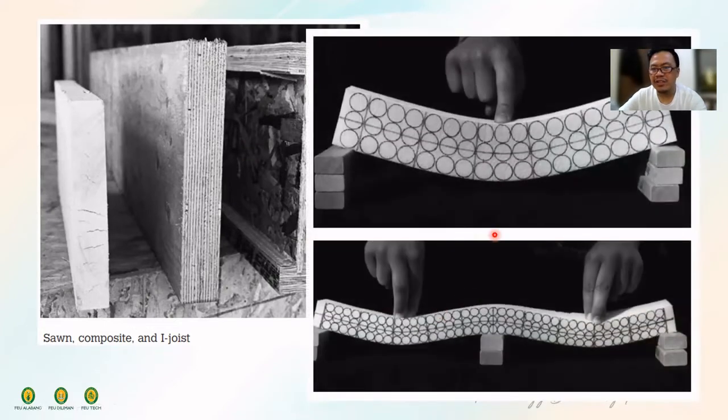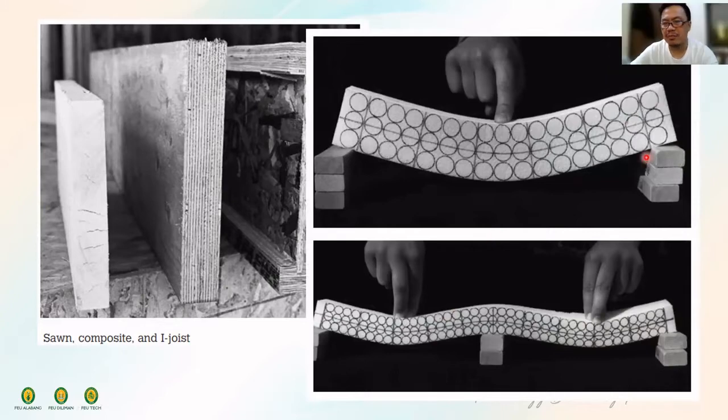Okay, so this is the concept of having the flexural stress on the beam. Let's say a beam. Pagka there's a concentrated load here, this could be the effect. This could be the elastic curve. This could be the possible deflection on the beam. So may elasticity, may elastic curve siya, no? Ganyan yung elastic curve. There would be a maximum deflection at the midspan, as we have studied it in the strength of materials, because of the concentrated load at the midspan.